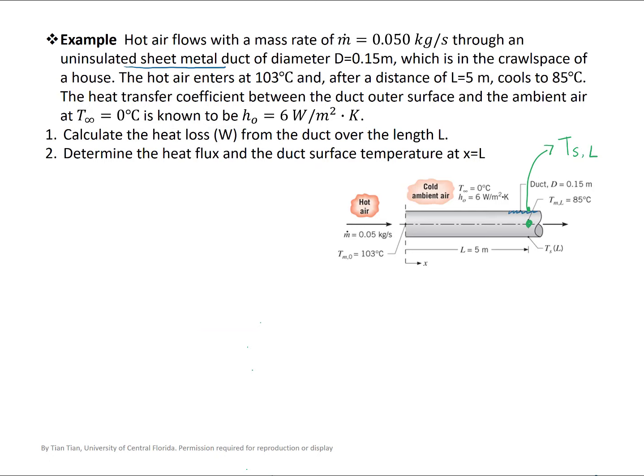Now we know the flow is turbulent. Next, we should check whether the flow is fully developed or still in the entrance region at axis L. How do we check this? Remember, we have formulas for calculating entry length. For turbulent flow, the hydrodynamic entry length and thermal entry length are of the same size. They are 10 times the diameter.